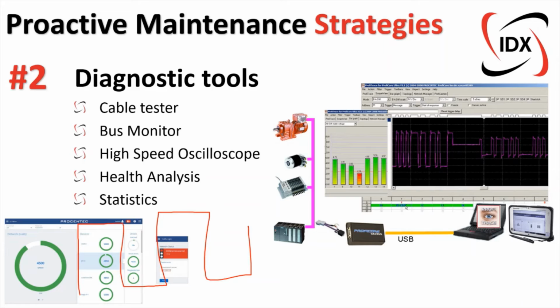Illegal messages is always a scary statistic. Illegal messages means that a telegram traveling along the PROFIBUS network has been damaged somewhere along the line. This could have been due to EMI, wiring faults, or duplicate addresses. Illegal messages are detected by a certain network component; a bus monitor would detect and count illegal messages and would tell you which device originated that illegal message or where it was due to go. It picks up illegal messages through detecting parity or bit parity errors in the telegram, or if the telegram does not follow the correct specification, such as the correct number of bytes, certain start delimiters, length indicators and so on and so forth.